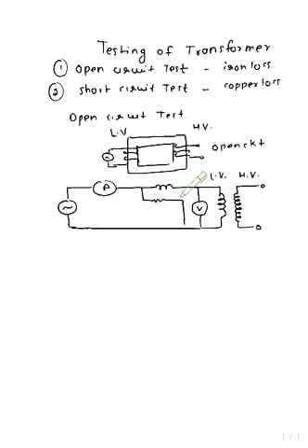All the measurement instruments are connected to the lower voltage winding, and this is called the wattmeter. The wattmeter will measure the power of the primary side, and it is connected in series with the ammeter. The ammeter will read the current, and this voltmeter is connected across the primary winding. It is used to measure the voltage across the primary winding, or supply voltage.